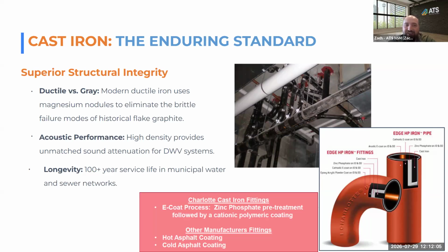Today, cast iron is mostly used in sanitary drain, waste, and vent applications. It's used in storm drainage, and can be used above and below grade. One of the reasons it's so versatile is not just its strength and ability to handle these applications and its durability, but also its ability to handle high temperatures. It can work up to 100 degrees C, and these are all non-pressurized applications.